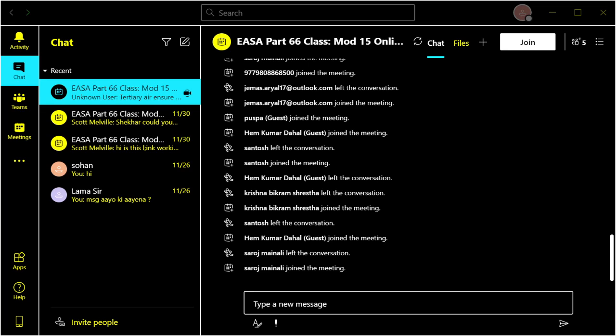Okay, and that's a base. I'm not going to speak too much about that one. It's just a total loss system. Okay, not much to that one then. Commonly known as a single shot. It goes flying and it lands before it runs out of oil. That's as simple as it. Very basic old system. So class is expendable, short periods only. There's no cooler required. No scavenge pumps because there's no return line. No return pipes, hence why there's no scavenge pumps. There we go. Okay, so very, very basic system. Nothing too much to worry about there.